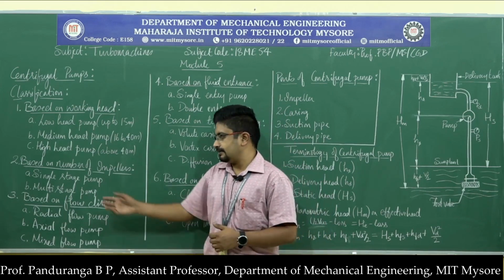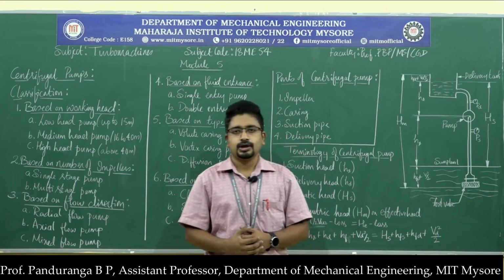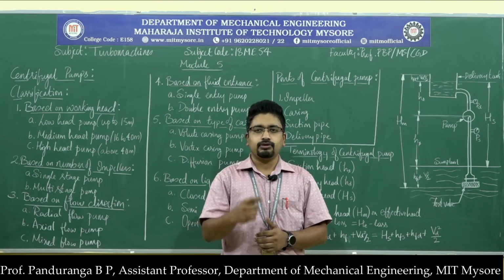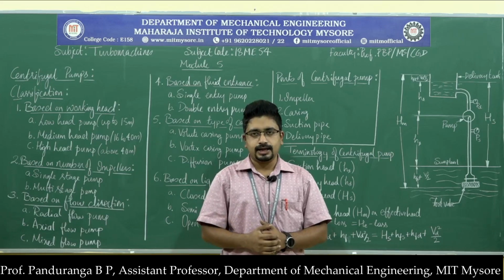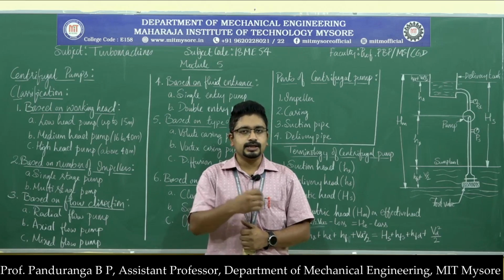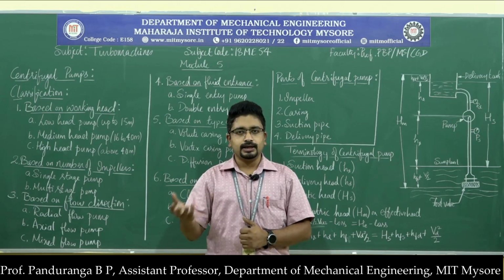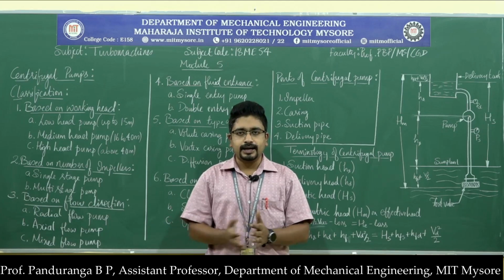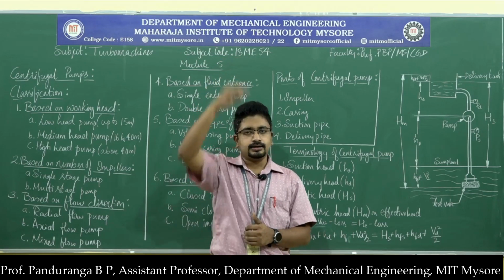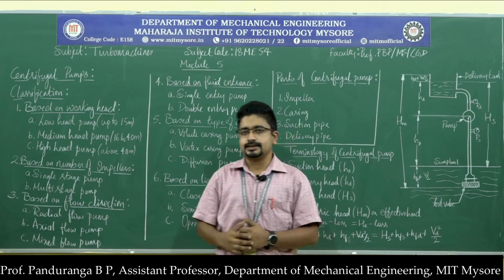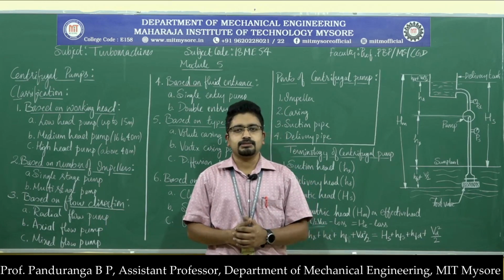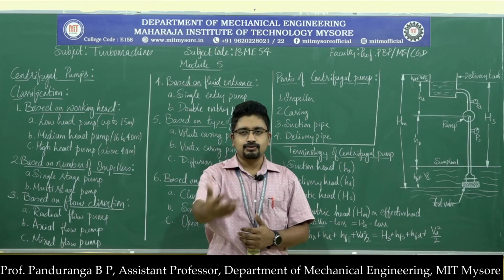If you have multiple impellers, there are two reasons to have multi-stage pumps. One is if you want to increase the head developed by a pump, then the output from the first stage of the pump will be input for the second stage of the pump. Thereby the head developed by the first and second stage will be added together, and we can deliver the liquid to a higher level than if you are using a single stage pump. Otherwise, in some cases we need to deliver a large quantity of water.